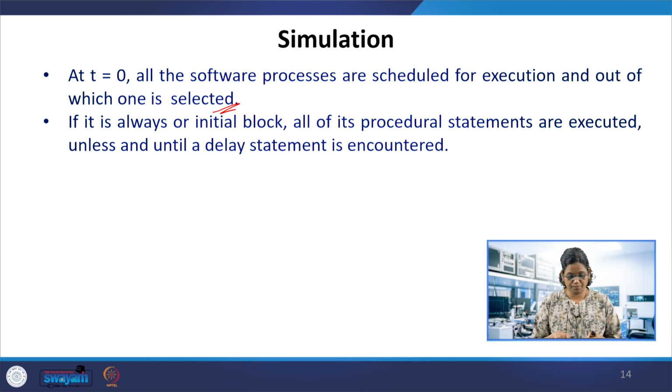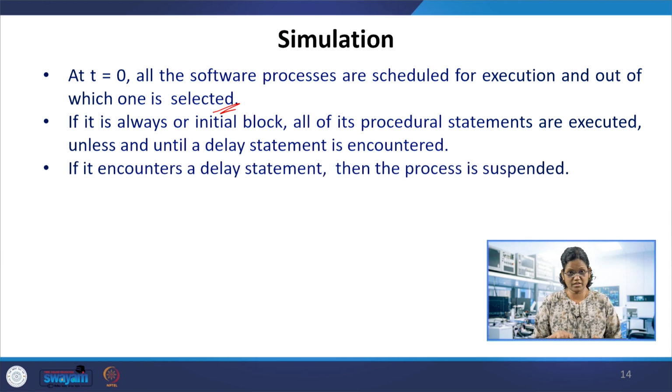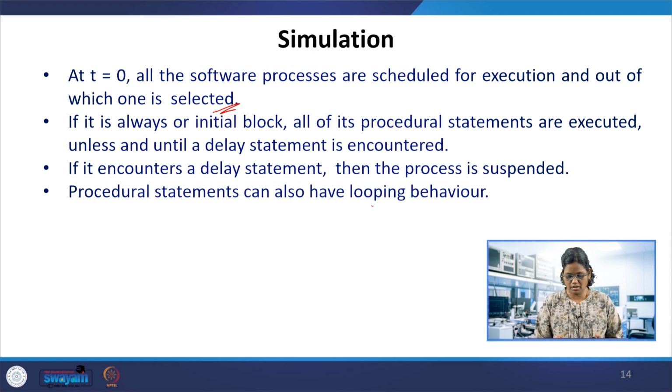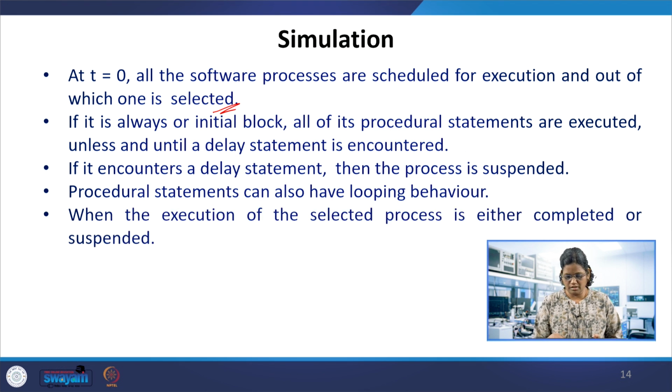If there is a delay statement in the always block, then the whole process is suspended. So it waits till that delay time, and then it continues. The procedural statements can also have looping behavior, so it can go into that and update other values as well. So those things have been taken care of, and then the process will be completed, or if there is any time delay, it is suspended.